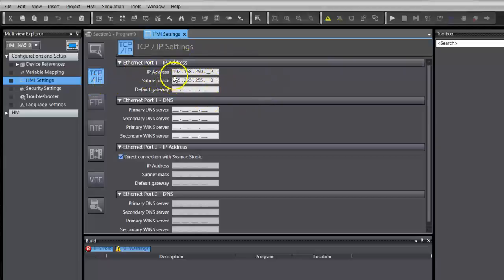By default, you would take it out of the box, connect, because it does have a USB port, but the way our simulators are set up in the lab, we don't have a USB cable into it. So the easy way is go to the configuration screen and just punch in an IP address, and then you can communicate with it for your program.